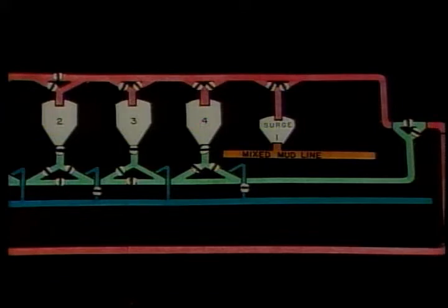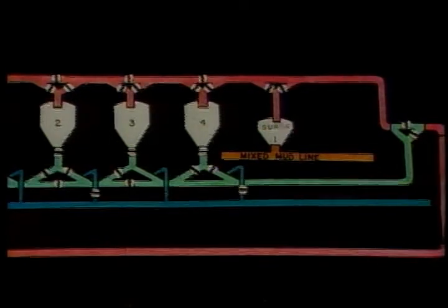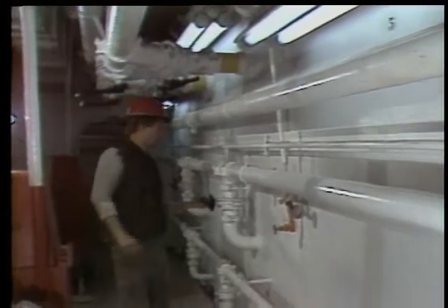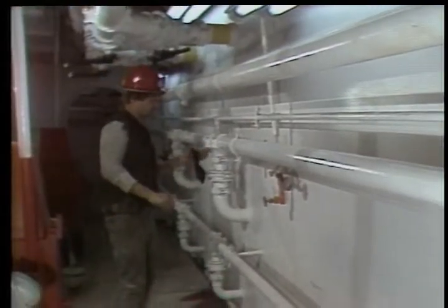When the transfer is complete, all of the valves are closed and the pressure is bled off of the source tank through its vent valve. Now let's watch a derrick man go through the procedures of transferring some barite. This is on the Sedco 471, so your system will probably be laid out a little differently.